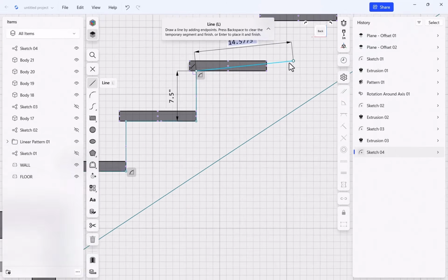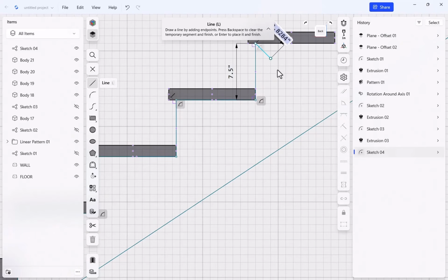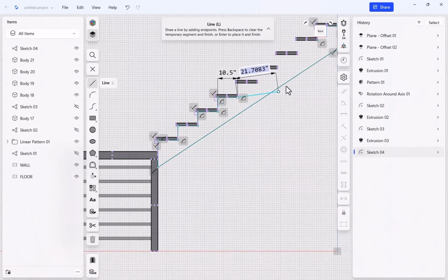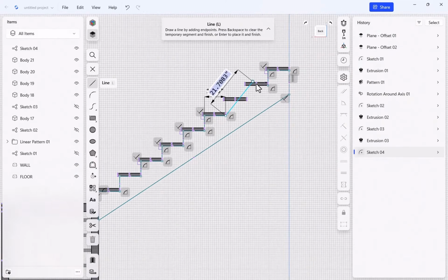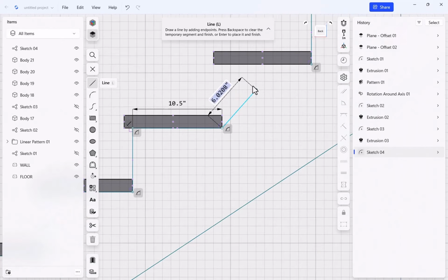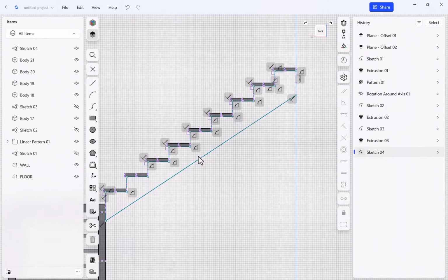And sometimes you might misclick here. It's pretty easy to do, but make sure you're getting that purple line saying that it is vertical, and you are getting a snap right to where you're trying to go. So I'm going to snap there, I'm going to snap there, and of course, we can speed this up if we wanted to. But if you have 100 stairs, you might be here for a while. Luckily, we have a fairly short staircase, but you can see here, as I'm getting back up to the shape, boom, now I've created one enclosed boundary, right? So my stairs go all the way to the top, all the way to the bottom.